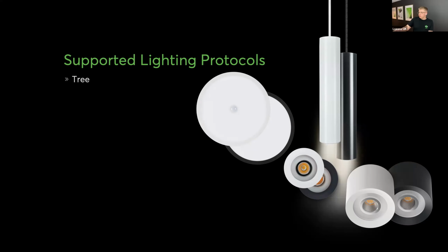I could have each of these 4 different types of fittings on one cable and control them all individually, because Tree gives us the flexibility of addressable lighting, things that we will be talking about a little bit later on. But not only can we control them, but controlling means dimming them, controlling the color, of course, on and off. But also we can then do mood-based lighting, and we can mix these together. We can put them in groups. We have so much flexibility, and it doesn't really matter how we wire them down the line.